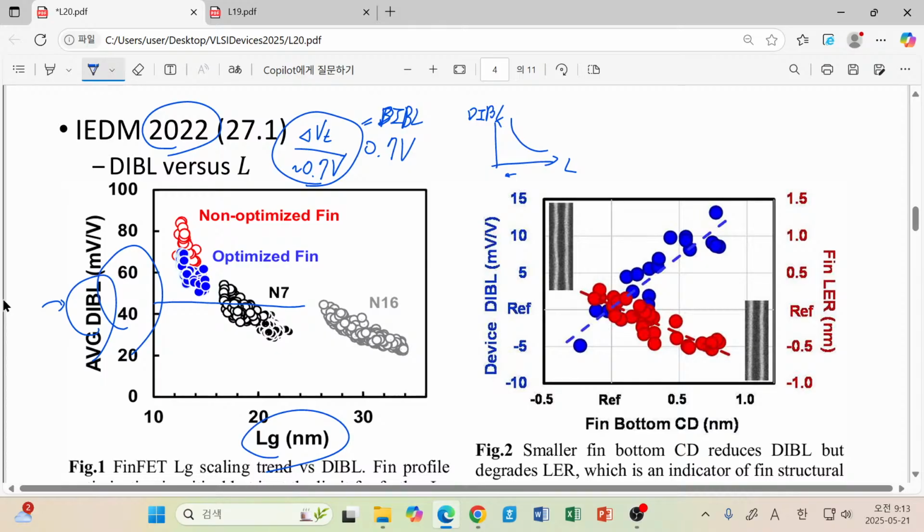In our previous discussion about short channel effect, maybe you remember, we solved the two-dimensional Poisson equation. After some discussion, we found that the minimum channel length which can survive this DIBL effect is about 2 times, like 3 Tox and WD. So maybe this corresponds to the lambda scale. At that time, we made a certain assumption.